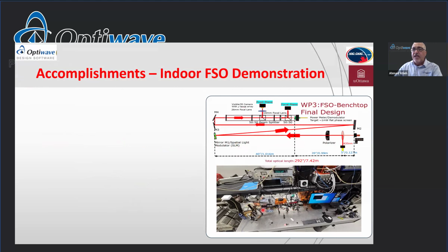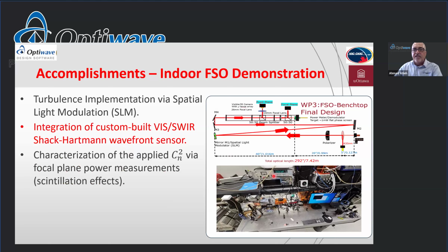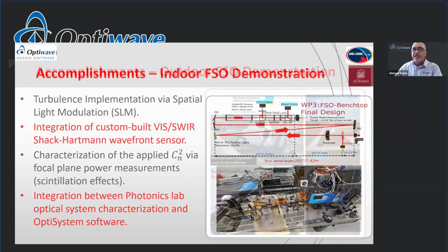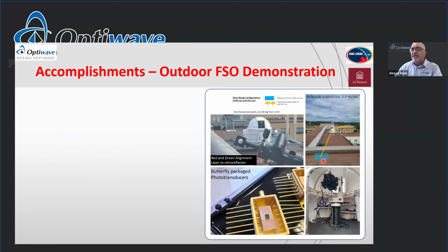We did some experiments in the lab for the system, where we did transmission, and we have a spatial light modulator to control the phase mask, and these are different characteristics of the analysis. And also we did a free space transmission through the light, as well as power beaming with high power lasers, like 15 watts, using photonic power converter chips.